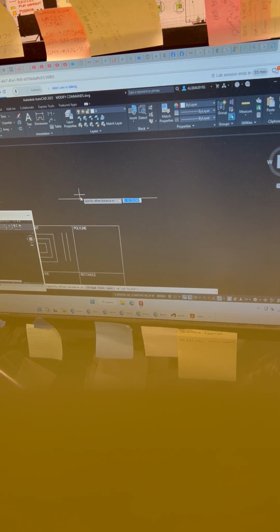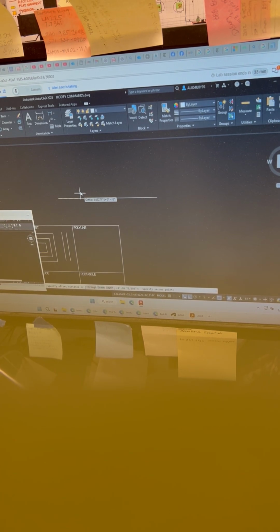I'm going to go ahead and offset this. I'm just going to pick a point above the line. And you can see now I have 2 copies offset precisely at 1 inch away. I see my students doing things like this all the time, and I can't figure out the psychology of it. When they go to offset something, and I'm going to click on this object to select to offset, they always, not always, but my students, they don't move their mouse that far away from the object.